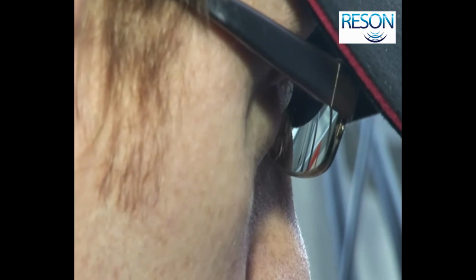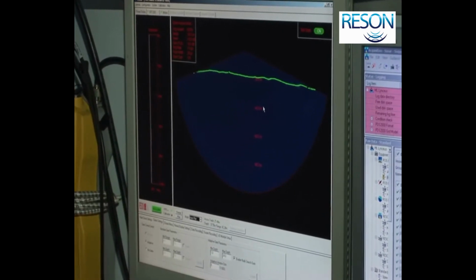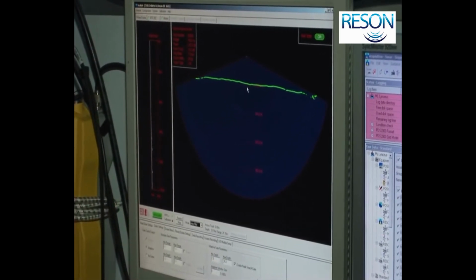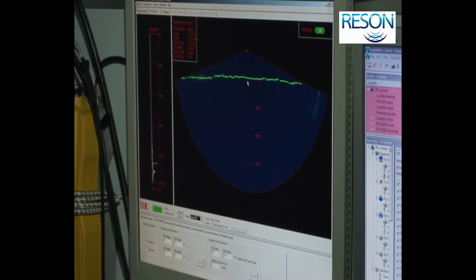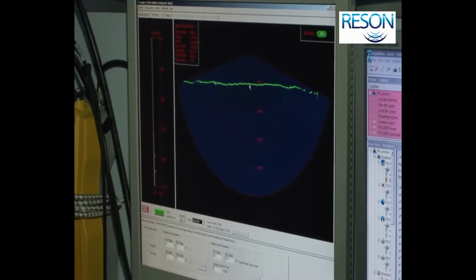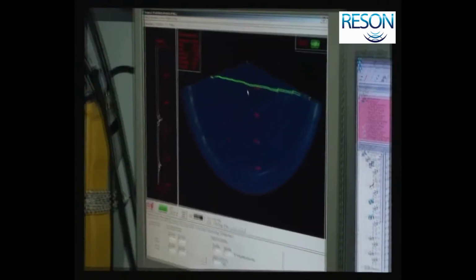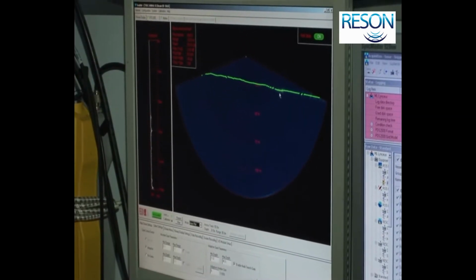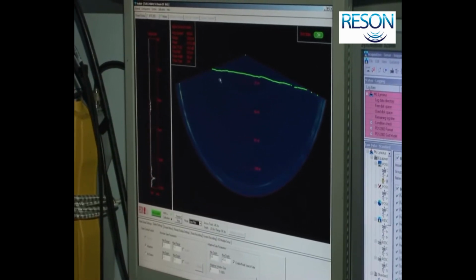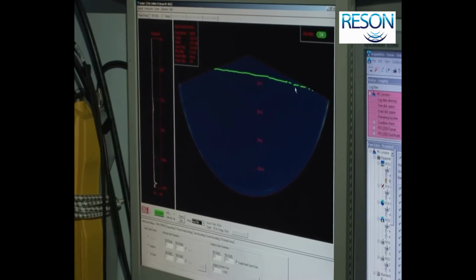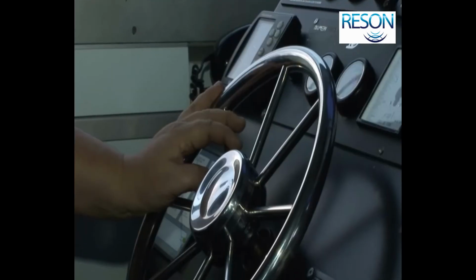You can see the range changing as we cross the channel, as it gets deeper now, down to 20 meters. The purpose of this being less operator interaction with the sonar. You can see that we are still in 511 equidistant beam mode, so we have full swath with uniform data density right the way across from one side to the other.